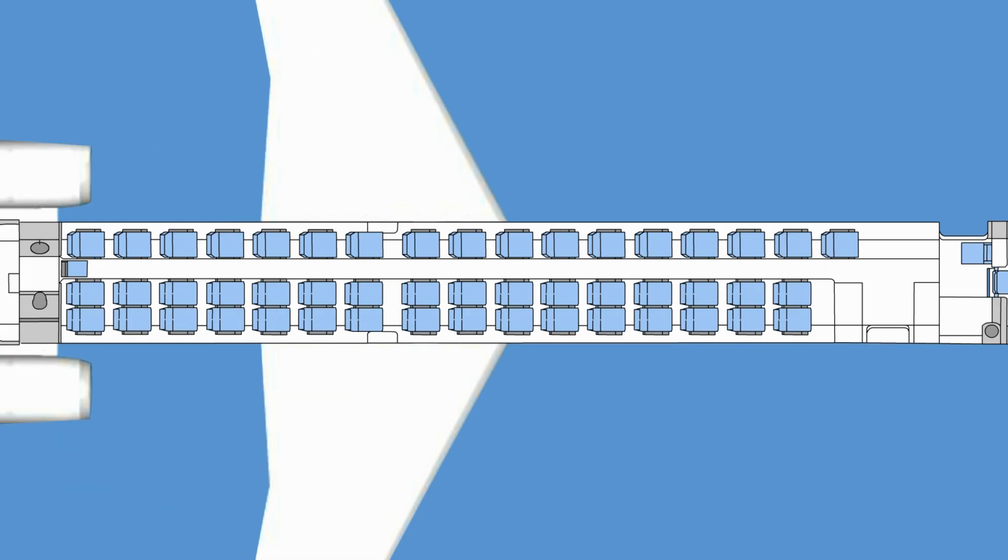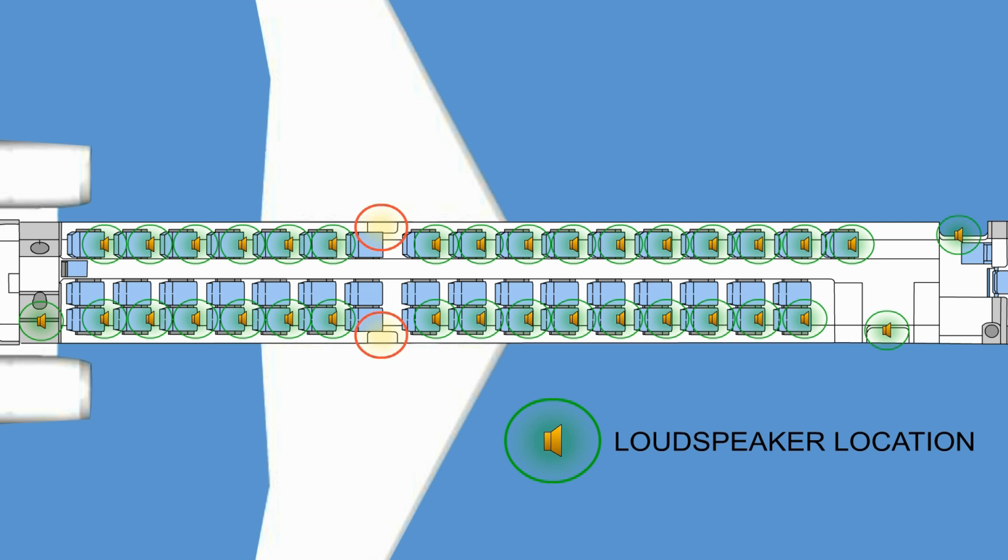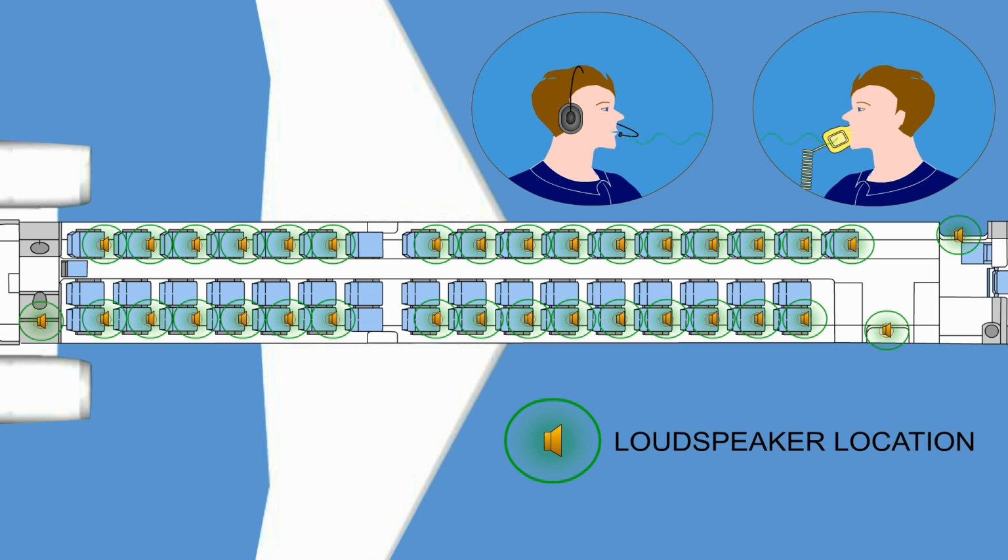The passenger loudspeaker system consists of one loudspeaker located in the ceiling at the main door, one in the ceiling at the service door, one in the right-hand cabinet in the lavatory, and one in each of the passenger service units. There is no loudspeaker in the passenger service unit located at each emergency door. The passenger loudspeakers work in conjunction with the audio entertainment and the passenger address and cabin interphone system. The passenger loudspeakers allow the attendants and flight crew to communicate with other flight crew members and with the passengers.